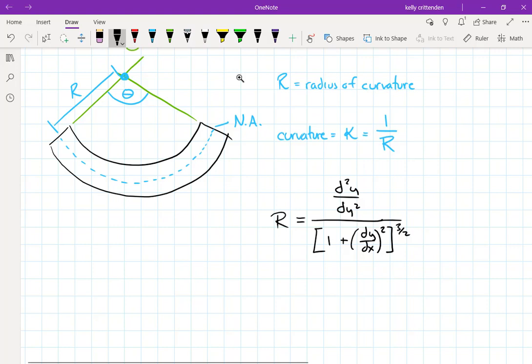So again, a beam in use is probably not going to curve that much. You know, it's not nearly the amount of curve that I've drawn. You certainly normally don't want your buildings to be wobbly like that. You want them to be pretty orthogonal. And so if I make that assumption, that's pretty valid. I don't want my beams or whatever I have in my machine that looks like a beam to bend that much. Then I can take this equation and notice right here, dy dx, I know what dy dx is, that's slope.